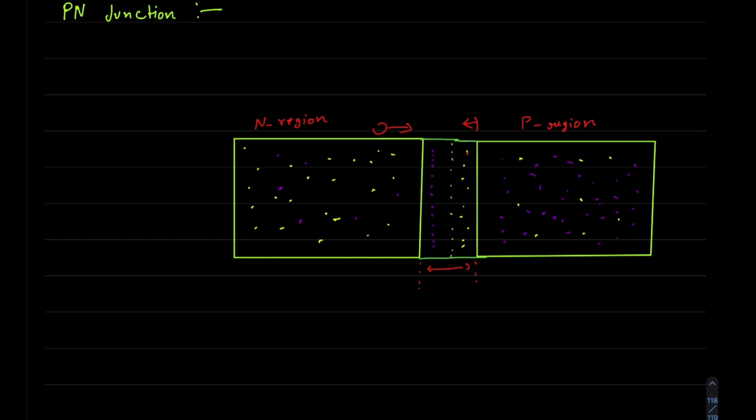This state of equilibrium will occur, producing a potential barrier zone. This repulsion between electrons will produce what is called a potential barrier zone around the area of the junction, as the donor atoms repel the holes, and the acceptor ions repel the electrons.